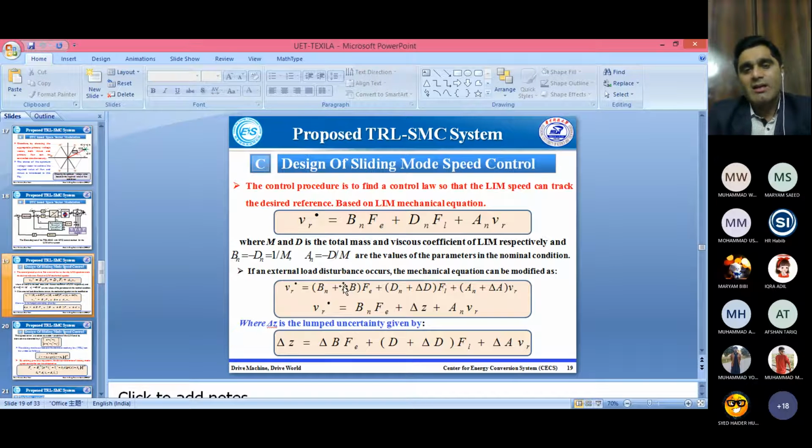In the reaching law or control law, we design an equation such that the state, from any place, reaches the desired value. For example, when the machine starts, it starts from 0 to the rated value, whatever reference you give the machine. Whether you give 5000 rpm or 4000 rpm or 1000 rpm, that is the reference, but the machine's initial state would be 0.